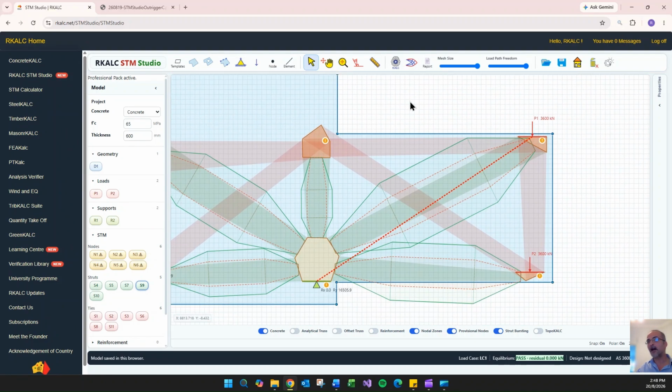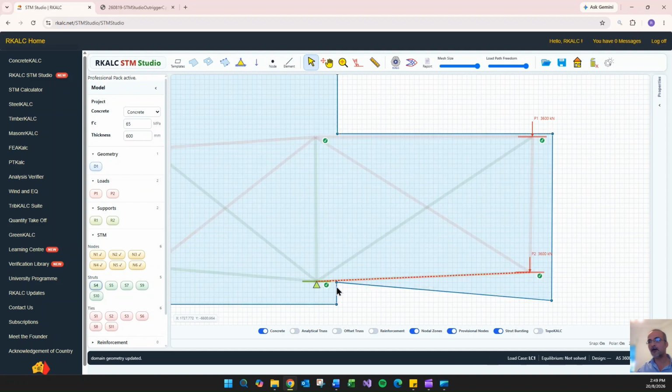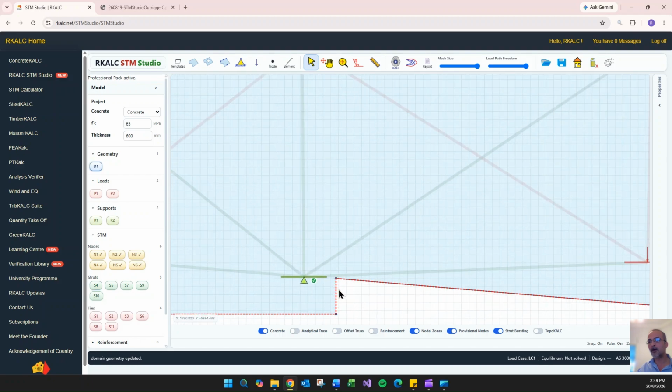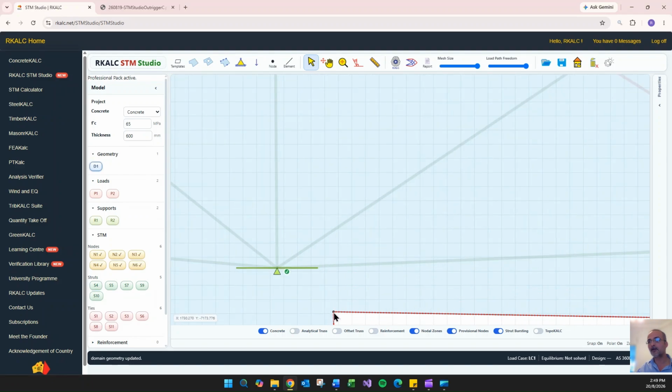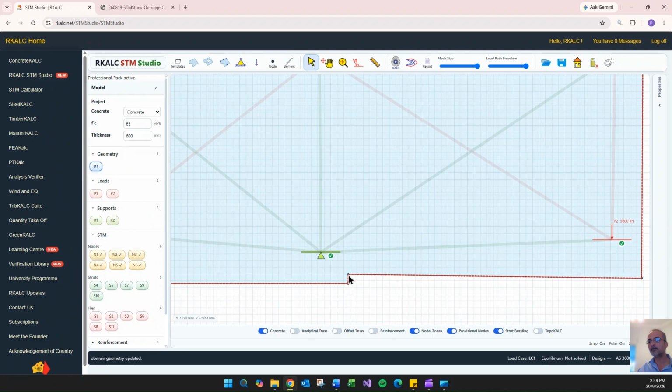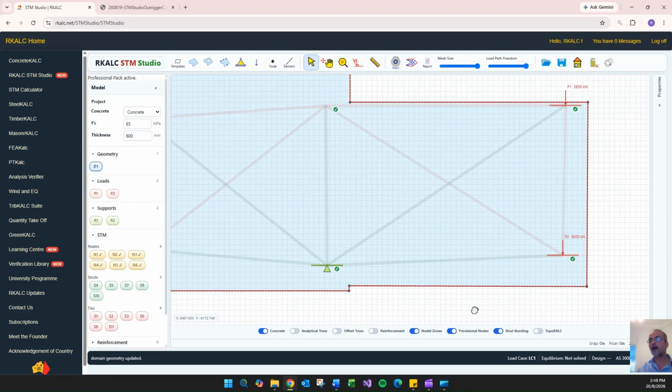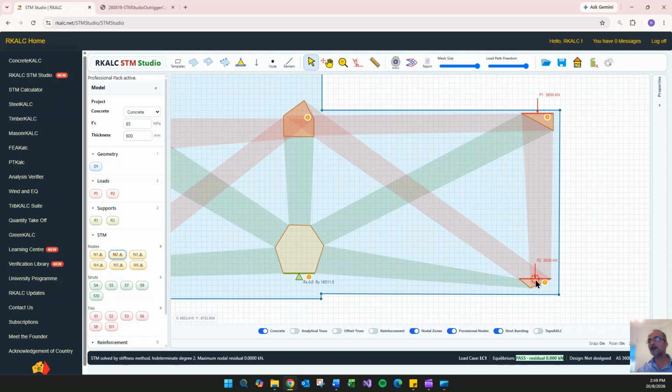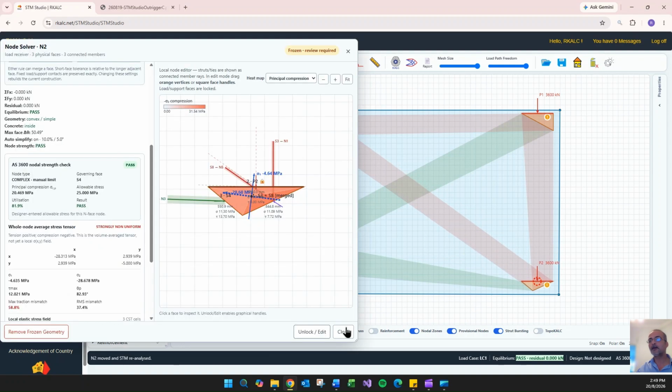So what is the height of the outrigger? From here to there is 6. And if I want to save it, I need to get probably a bit more height. And this is making sense. So if I just take that, make my structure slightly bigger, that would be the call that you will make as a structural engineer. And then increase the truss size.